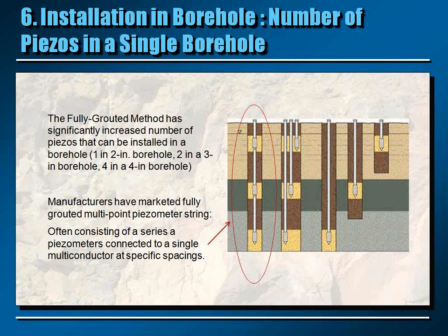These piezometer strings normally consist of a large multi-conductor cable to which are attached various piezometers at specific spacings. So with this type of instrument, it's possible to install many more piezometers in a single borehole.